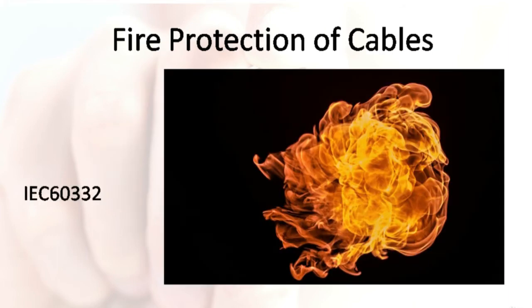For both the data and electrical cables, PVC, or polyvinyl chloride, and PE, the so-called polyethylene, are the most common insulating jackets being used. These jackets are combustible and have a probability for propagation of fire, and this is more prominent when the cables are bundled together. Now, fire protection of the cables in your mining farm is really not a must-have, but it's good to keep it in the back of your mind when you are choosing cables for your mining facility.